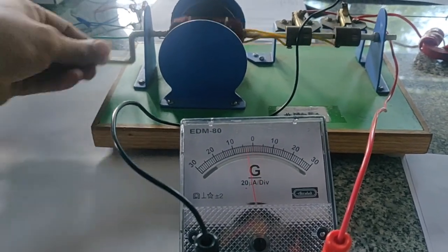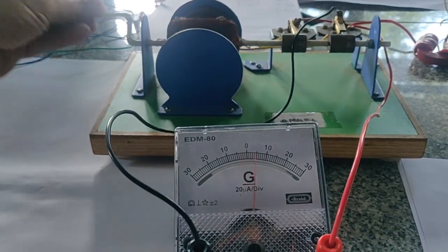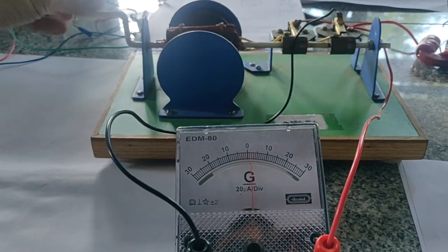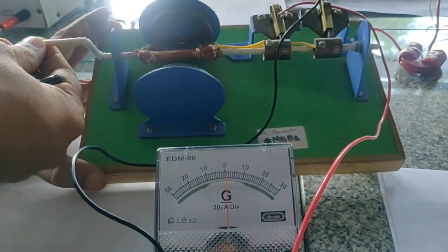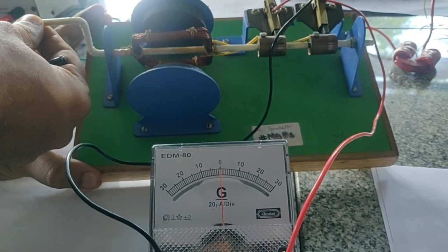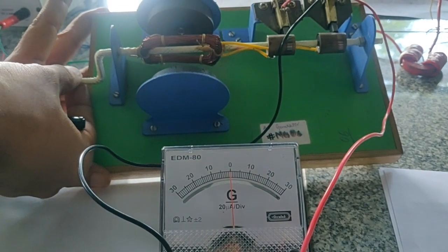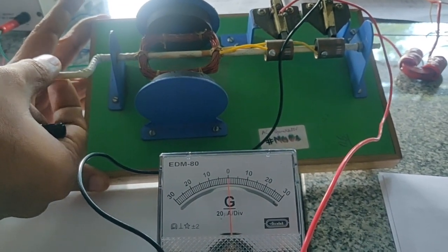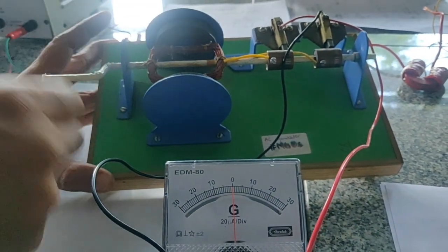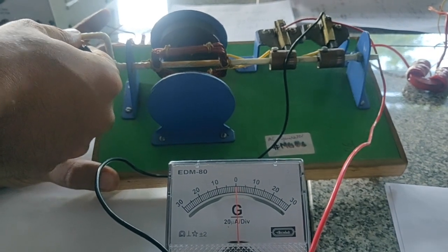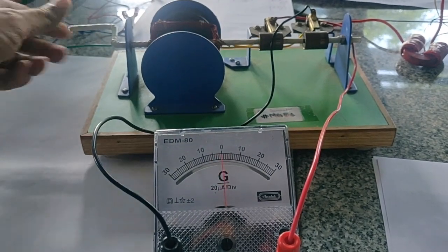So you can see that there is a voltage that's fluctuating in both directions, right? And the reason why that happens is because there is a changing magnetic flux. As I rotate this coil, you see that the magnetic flux is maximum here, and it reduces as I turn here, and as I turn here it again increases, and as I turn here it reduces. Here it's zero because there's no field line that passes through this area, because this area is horizontal to the magnetic field, and as I increase the angle, it changes. So as I keep rotating it, you will see that these fluctuations happen, right?